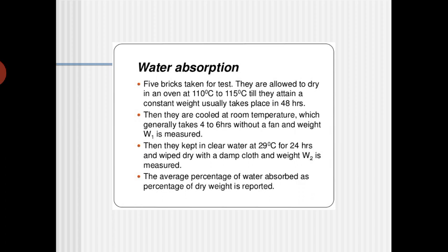The temperature of the water should be maintained around 28 to 30 degrees centigrade, and you have to immerse the bricks for about 24 hours, and wipe them dry.